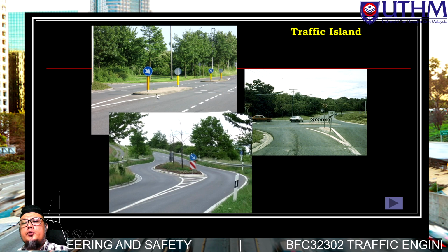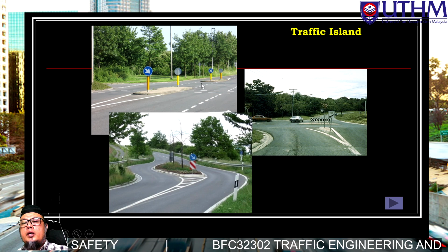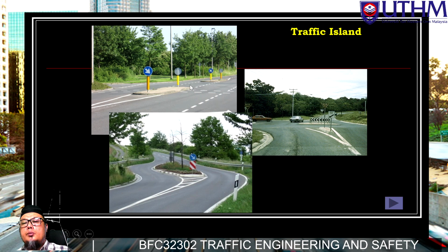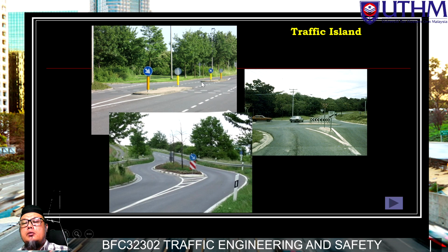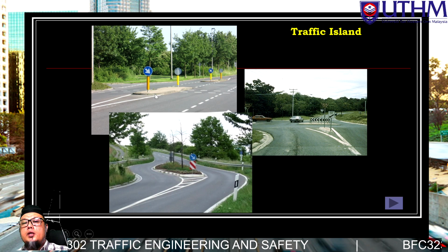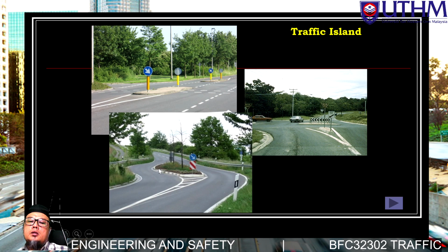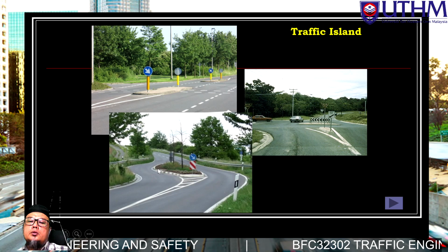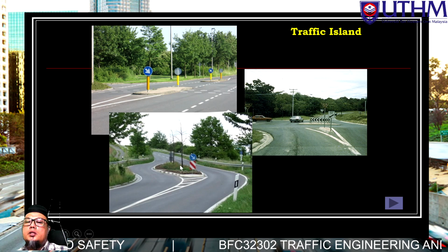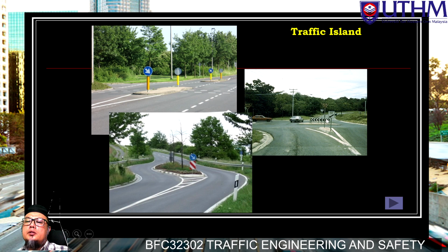it to apply for pedestrian refuge as well. This is an additional lane or right turning protection lane, for vehicles exiting the main road to enter the minor road; they have a right turn protection lane. This one is for pedestrian refuge. This is a traffic island but it is not very high. Okay, this one is also similar, I think a crossing for pedestrians or cyclists. This one has some beautification with soft landscape. This one is typically a directional island, as